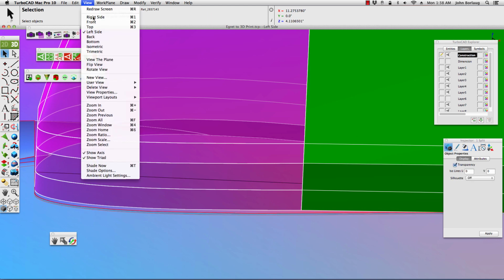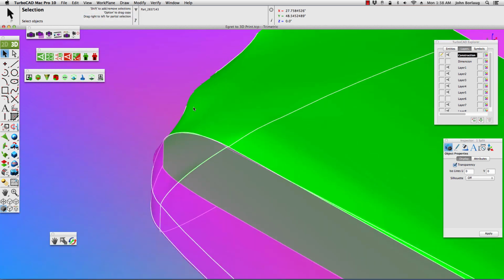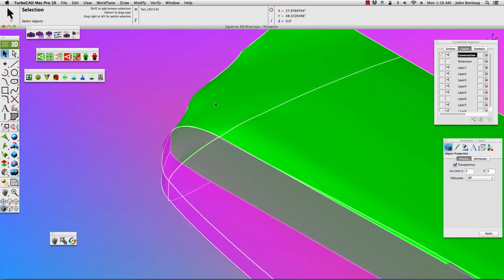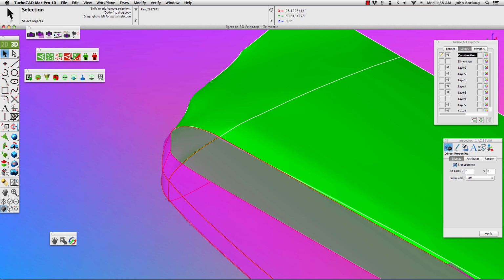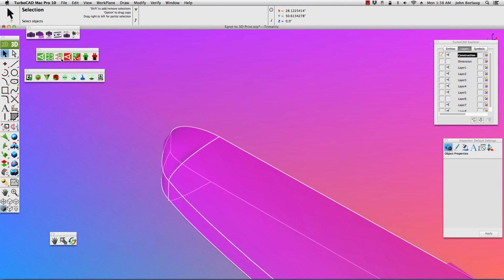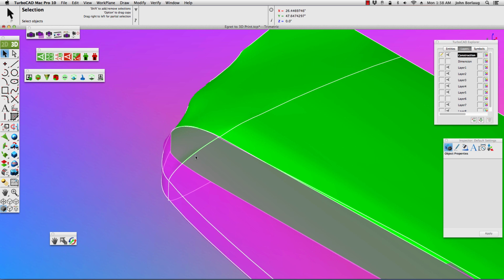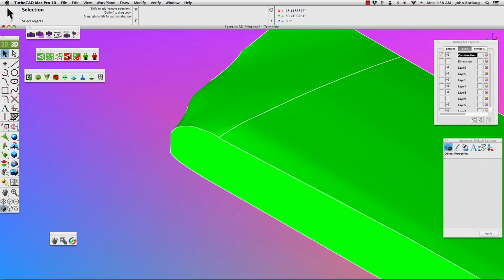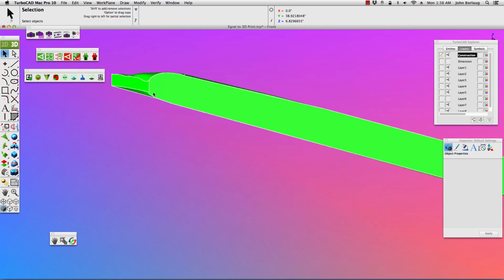And coming on into our trimetric, where I had some lumpy spots was if I go and hide that one, whoops, edit, undo, hide the red one. You see these lumps here. What I had to do was come in and add the pressure deform at 50.